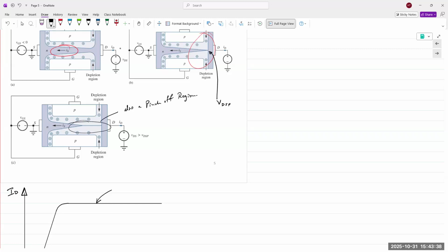But when it comes to JFETs and FETs in general, if you're talking about pinch off voltage VP, which is on the spec sheet, then we are referring to VGS and not VDS, right? Because VDS can have multiple levels. VP is measured with no applied VDS.